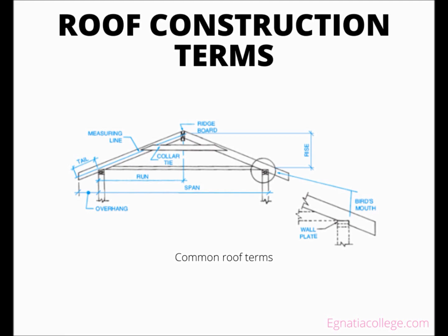Although most modern roof frames are built with trusses, it is valuable to know something about rafter-framed roofs, because some special situations call for rafters to be cut and installed on the site. The run is the horizontal distance covered by one rafter. Run does not include any part of the rafter that extends beyond the wall. On a common two-sided roof with both sides having the same pitch, the run is 1/2 the span.